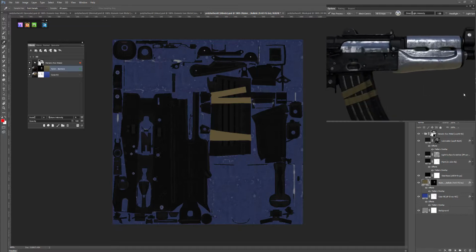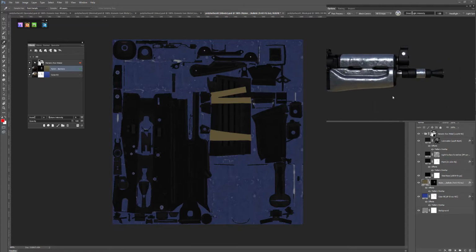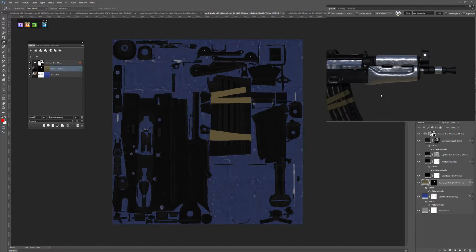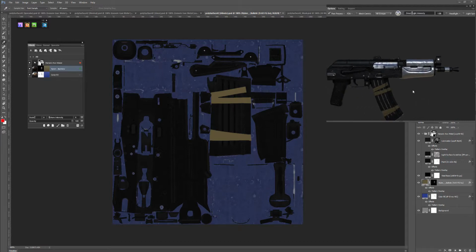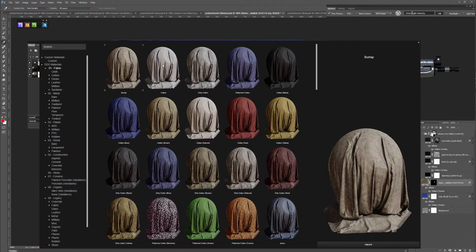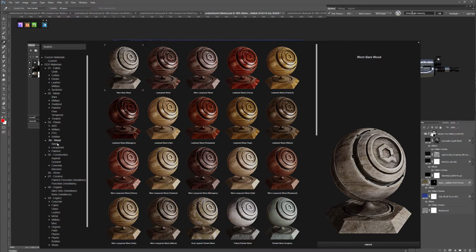Okay, so obviously this section here is supposed to be wood, but is metal, and it's very odd. So I want to change that. So instead of creating a smart material and then applying it to a certain ID group, I have a faster way to do this. Hold down C and Shift, and we'll click on that material ID, and that brings up my smart material. And I want wood texture.